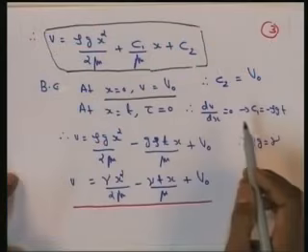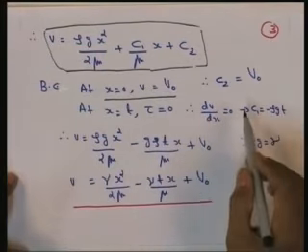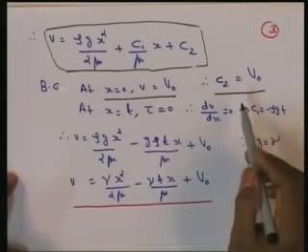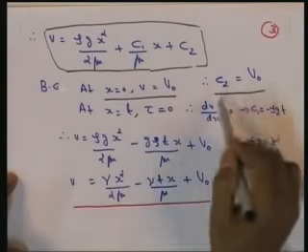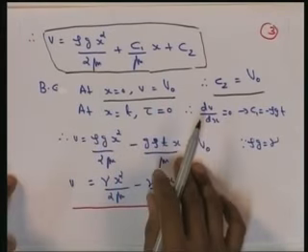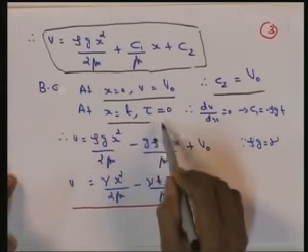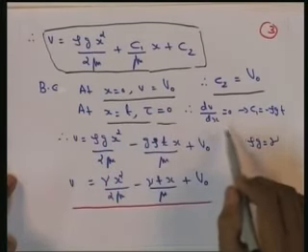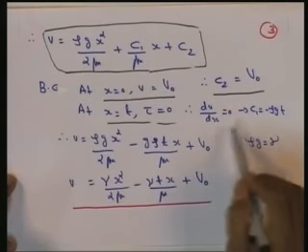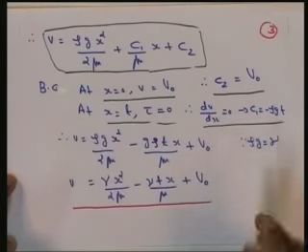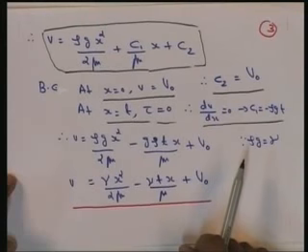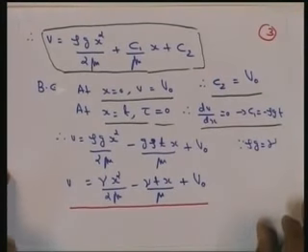The first boundary condition is x equal to 0, v is equal to capital V 0, from which we get c 2 is equal to v 0. The second boundary condition is at x equal to t, tau is equal to 0, so dv by dx is equal to 0, from which we get c 1 is equal to minus rho g into t, where g is the acceleration due to gravity and rho is the mass density of the fluid.